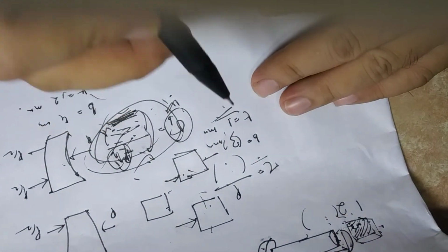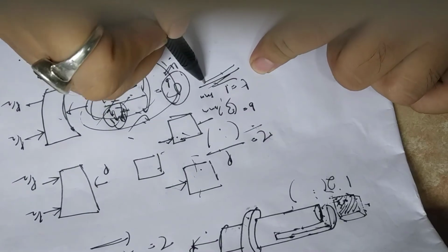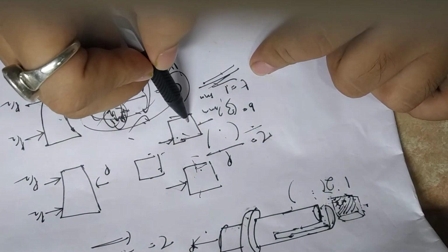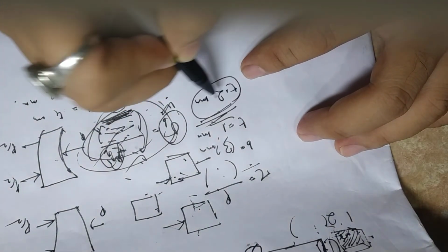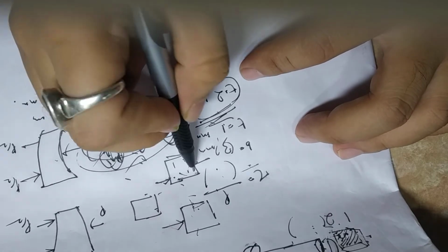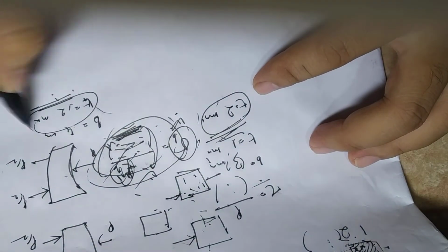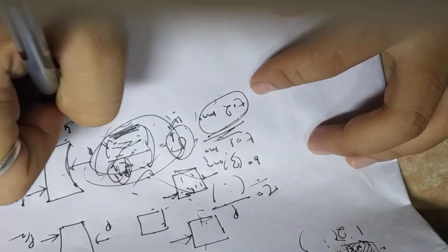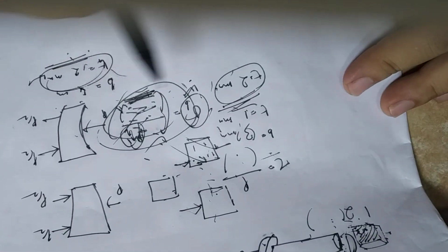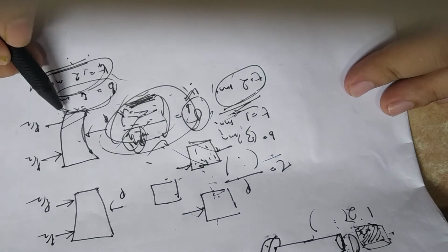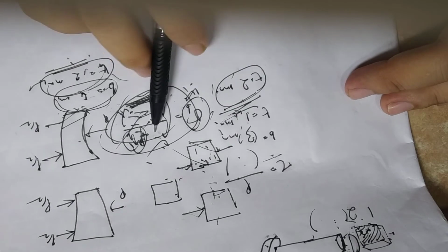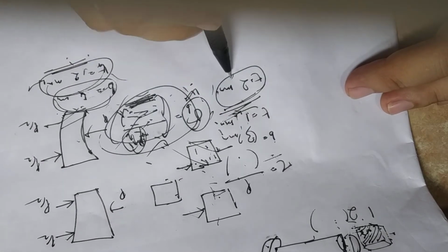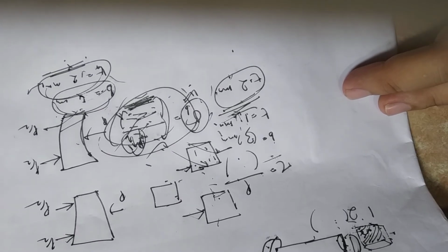Now the thing is, if we take 1 mm, this will be safe in case of breaking. But if we take 2 mm, then also it will be safe, isn't it? So the logic is, if you take a higher value, it will be safe for both the cases. Otherwise, if you take a lower value, it will not be safe in this case. So you always take the higher value. You have to find both using both the formulas, find out the dimensions, and take their higher values. So in this problem also you'll have to do that.